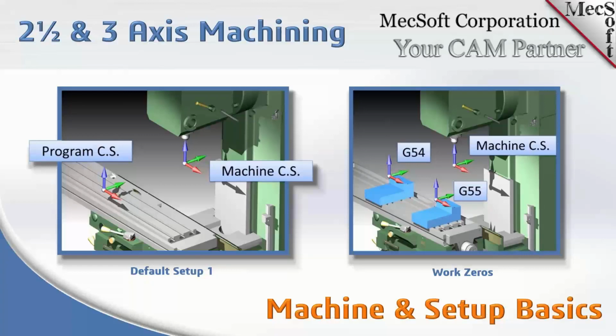So on the right, in addition to defining a setup that matches the coordinate system of your machine, you can also add what we call work zero. By default, when you open up a new drawing or model to machine, like I said, the setup one is aligned with the world origin. Also, that becomes the zero origin location to calculate your tool paths.